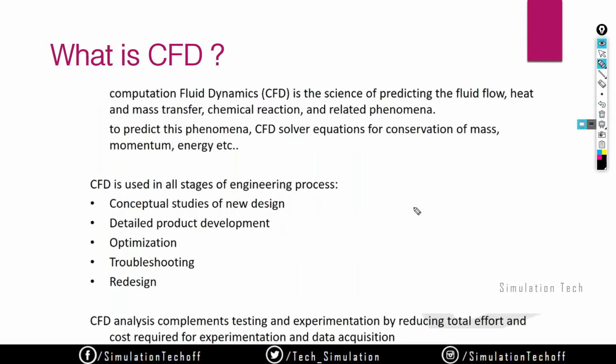Throughout this we have various validation methods. That is analytical method, numerical method and experimentation method. The analytical method takes much time, and when the problem is too complicated, the solving time also increases. The experimental method is okay, but it is time taking and very expensive cost wise. That is why we don't usually use experiments, but occasionally we use this experimental method. At the last stage of the analysis, most of the time we only depend upon the numerical method. CFD also comes under the numerical method. So that is why it is very economical to use CFD analysis.